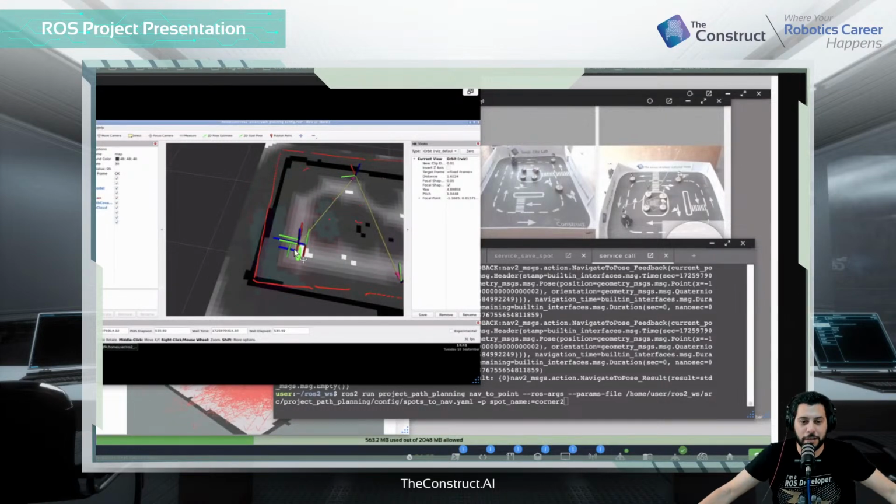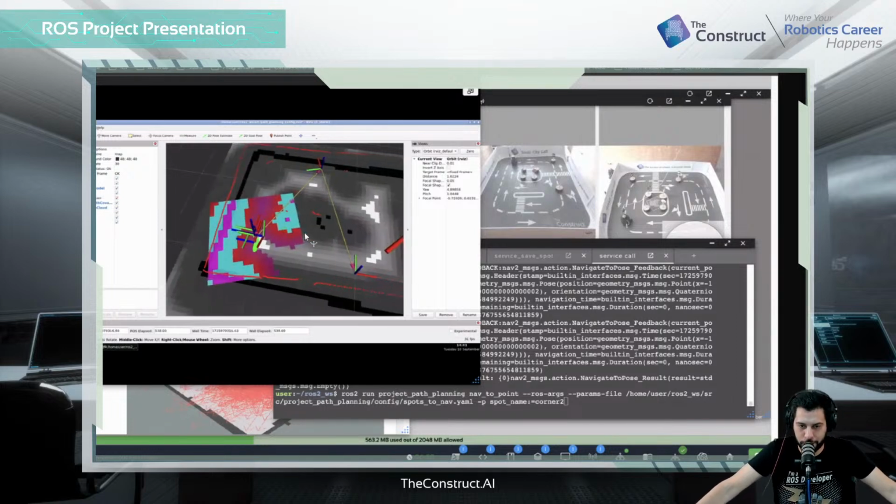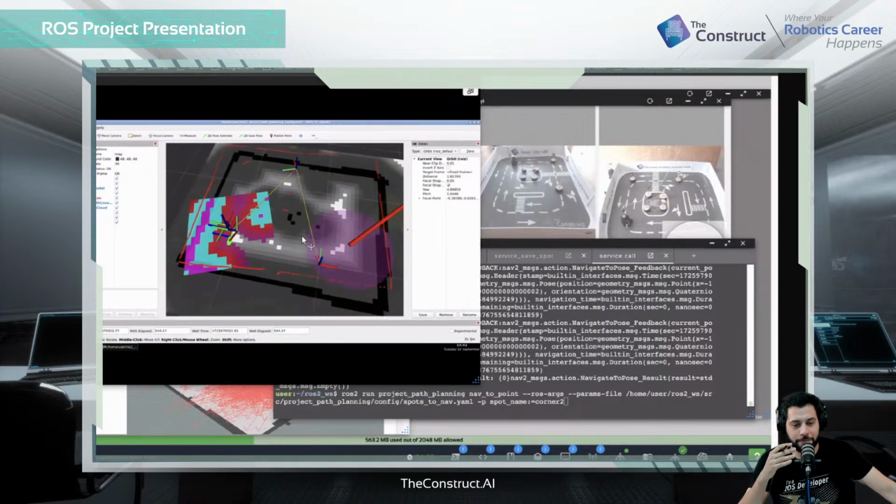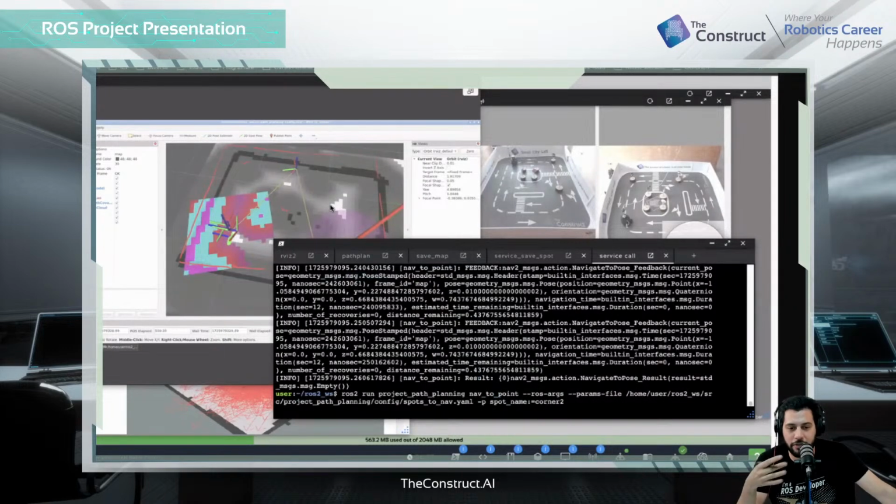Yes, that's most likely because we're not publishing the robot description file that you can then load into the robot model element in RViz. So if you were to download the URDF and then add it as a file, you would find it.